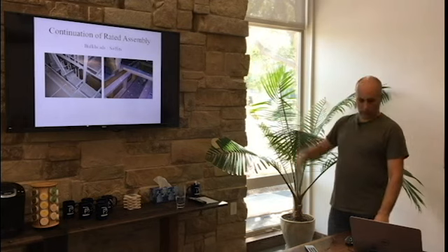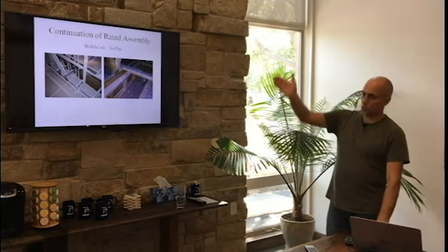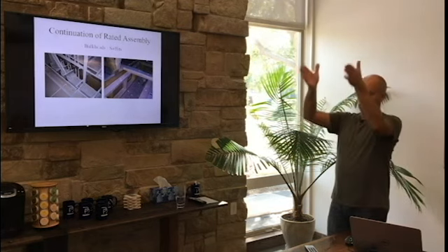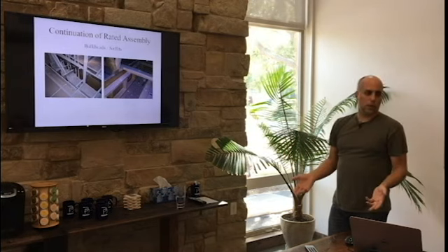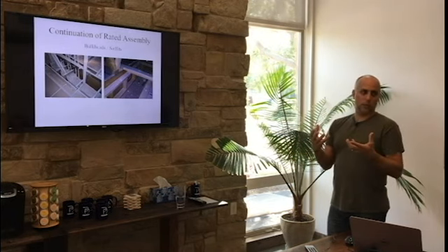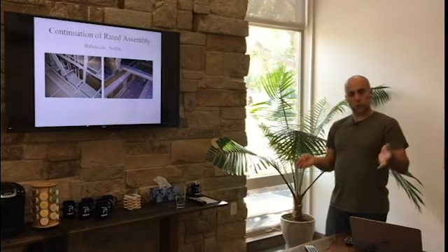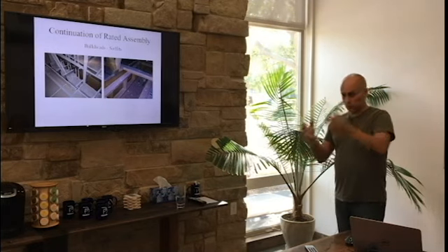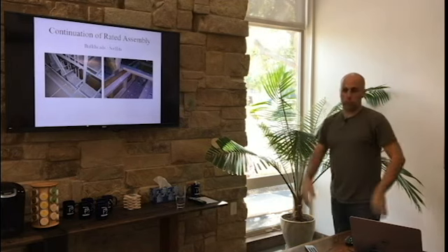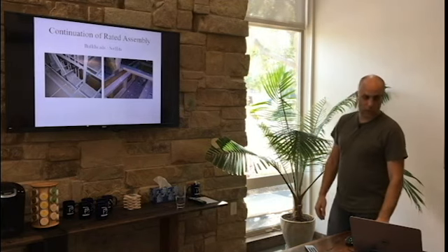So we do, and I'll show you in a second, but that includes all the bulkheads. Just because it looks vertical, it looks like a wall, no, it's not. If it's roof structure behind it, it's a roof, and you must treat it that way. If it's a bearing wall that you're looking at, and it's in the attic, then you better treat it as a bearing wall, and you better have gypboard on both sides all the way up it in the attic.